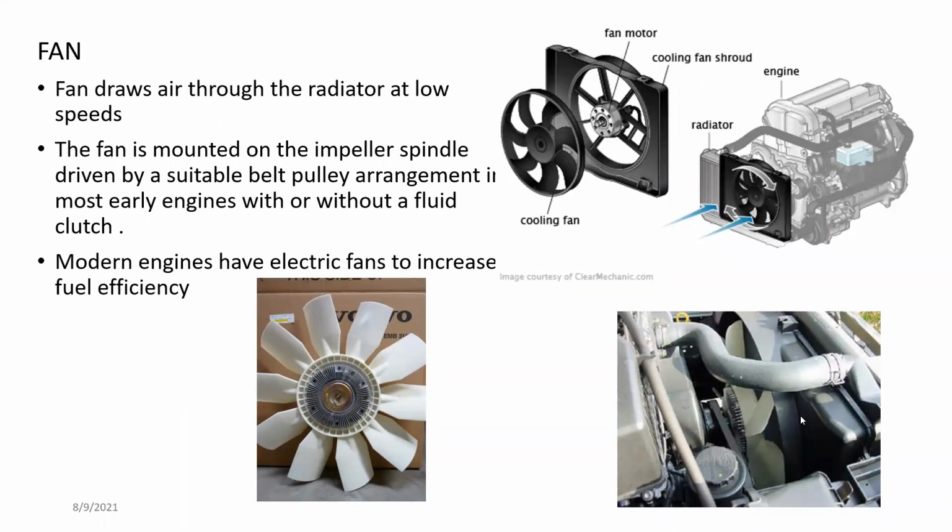So basically, most of the newer versions, like front wheel drive vehicles, have the engine fixed in a transverse layout, right? When the engine is fixed in a transverse layout, cooling of the engine is difficult because a mechanical belt driven system is difficult to use. In such cases, these sort of electric fans are used, but in the other longitudinally mounted engines, they mostly use this fluid coupling type.